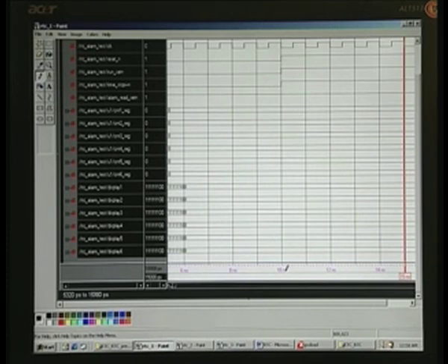And you see that at 10 nanoseconds, we had taken 100 units of time, after that only we start the real operation. Reset, which was active here, is made inactive so that the normal operation starts, and simultaneously we set it to run mode as well as time mode. This is run and time, so it is set to 1 here, and we should also set alarm read/set to read position. You should not put it in set mode. If you do this, you will not get the display, and it will freeze at 0. You can notice that by changing your test bench.